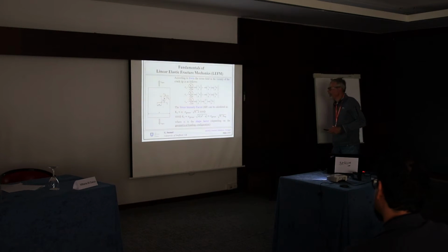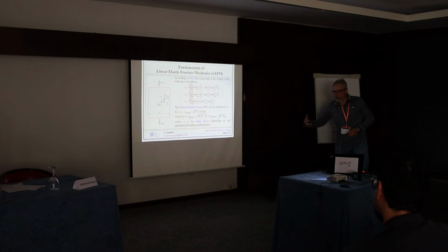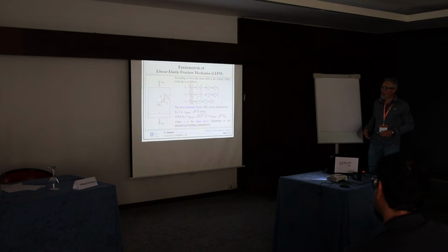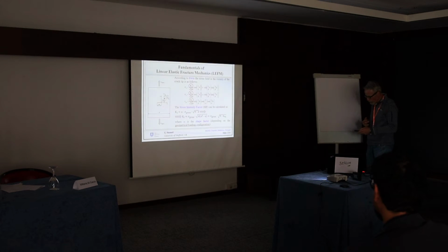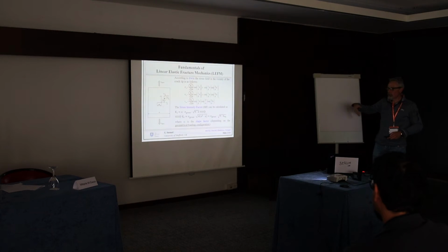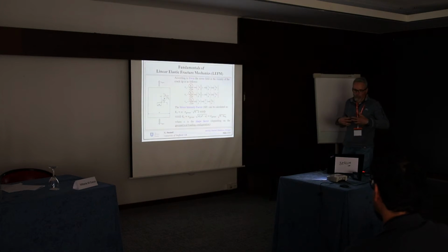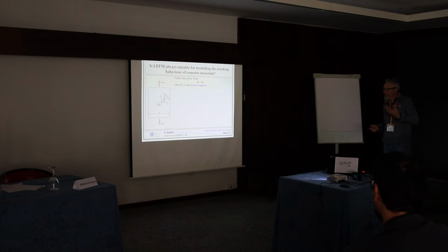Why is that relevant for what we are going to do? Because basically this is a way to bring any fracture mechanics problem back to the problem of an infinite plate containing a crack loaded in tension. This is the reason why we like to approach the problem this way. So this is nothing new, this is what we know, and how can we use this body of knowledge to model the presence of manufacturing defects inside of 3D printed concrete? Actually, we need to take a further step to do that.